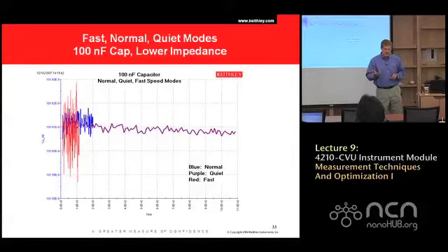When I say that, what I mean is our AC impedance meter is calibrated to national standards: NIST standards, Japanese standards, European standards. We have a traceable standard. We actually had to go invent a 100 nanofarad traceable standard. It didn't actually exist. So that was the biggest standard that we could get, and that is the last calibrated measurement that we can actually verify to a standard. 100 nanofarads is not the biggest capacitance we can measure. We can measure up to hundreds of microfarads, but we just can't trace them to a standard.